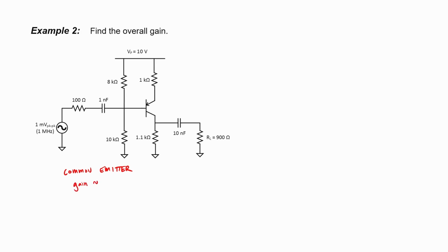The expression for the gain of a common emitter amplifier after you've dealt with the input stage is basically just the resistance seen from the collector divided by the resistance seen from the emitter. With NPN transistors, we're used to seeing the collector resistor up here and saying this resistor divided by this resistor gives us the gain. But here you have to invert it, right? Because the collector's at the bottom.